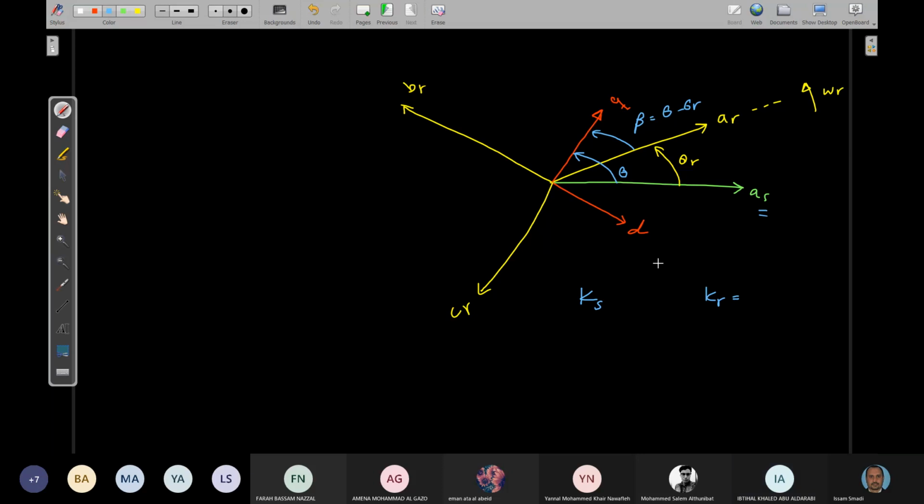Okay. And in the end of the day, I need to attach the frame. I need to align the Q or the D in a certain direction in order to achieve something. And this is, by the way, very good in order to pave the way for the vector control. Because in the field-oriented vector control, I'm having meaning for the reference frame. I'm attaching the reference frame, for example, such that the d-axis of the reference frame is pointing toward the rotor flux. And let's see what advantage I can get from there.